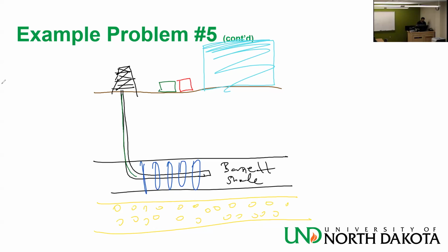How about we come here, we drill another well, a smaller well, vertically down, and we will take this water that we produce and inject it down to the Ellenberger. We call that well a saltwater disposal well, SWD well.